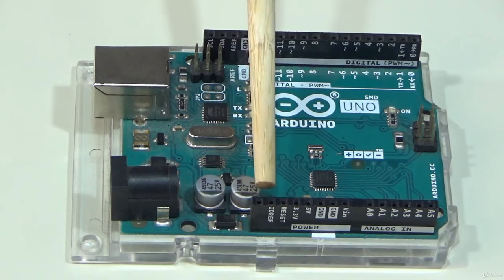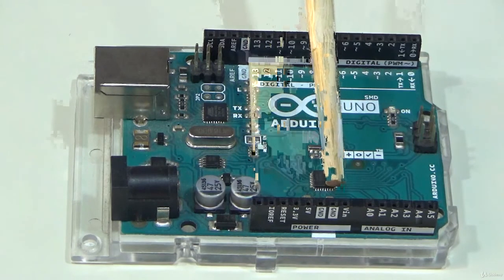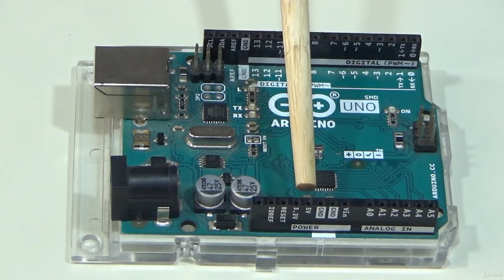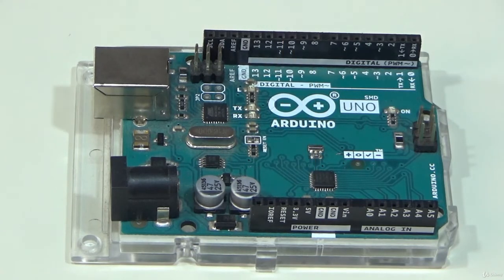and these are the power related pins. Here V in, you can apply external voltage here, 2 grounds, 5 volt, 3.3 volt, and external reset if you want to connect, and the external input output reference.